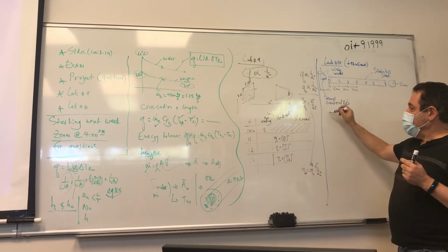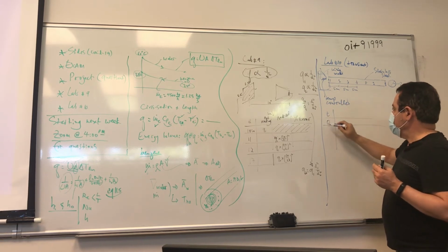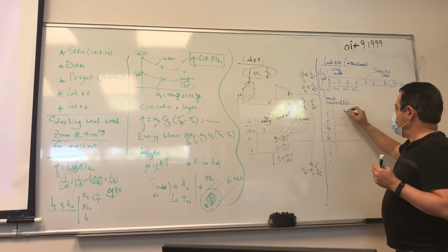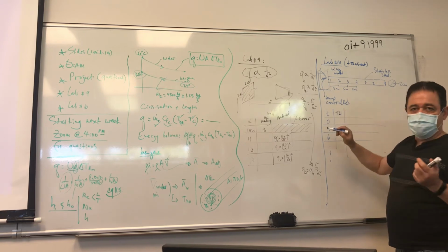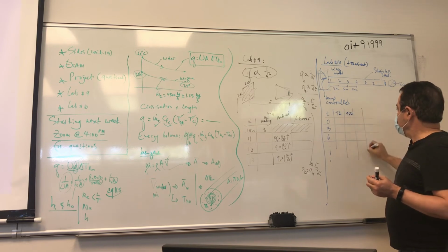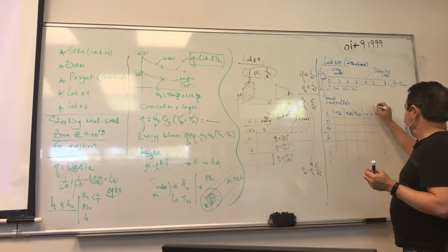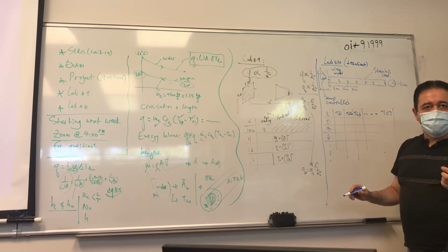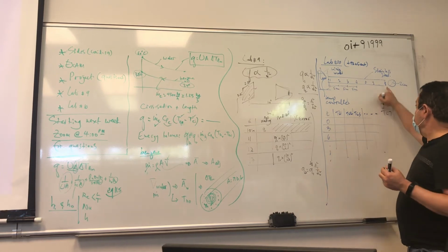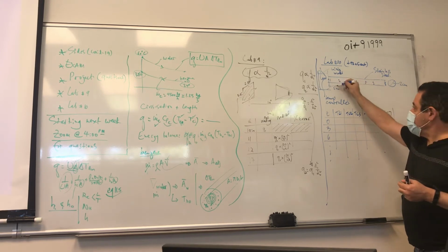The only data we're going to be taking is that when t is equal to 0, and then every 3 minutes, we're going to read the temperature at thermocouple 1, thermocouple 2, thermocouple 3, all the way to thermocouple 7. We're just going to read those values for the temperatures. Because it is a function of time, obviously the far node is not going to feel much until maybe some time later. Most of the action occurs here.